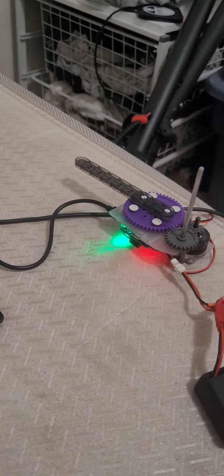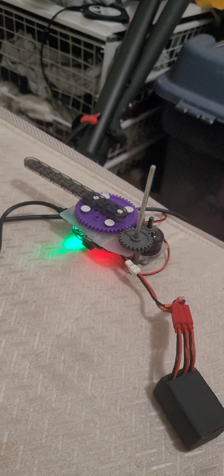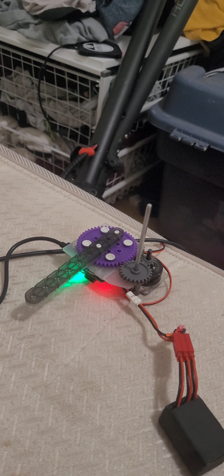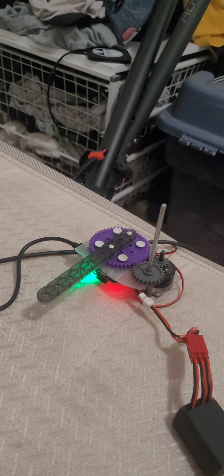The initialization starts. It moves till it passes 0. Once it passes 0, it does some math. The code doesn't really work as intended, but it does work enough. So, what I can do is run a test. Right now the motor is at 0 degrees. I'm able to mechanically move it to 0 degrees where I want it to be. From there, I'm going to point my camera at the motor and tell it to go to 90 degrees. So 90, enter. As you see, the velocity is stacked all the way up, so that is maximum speed.